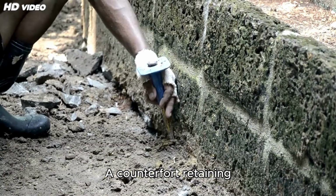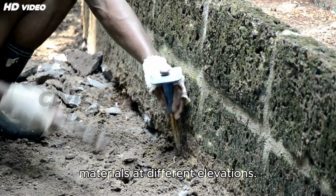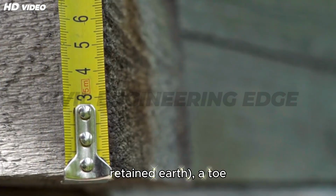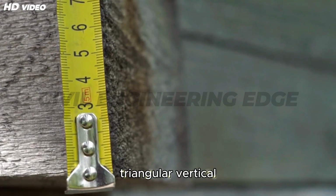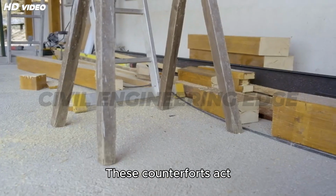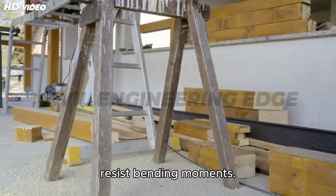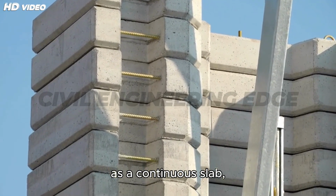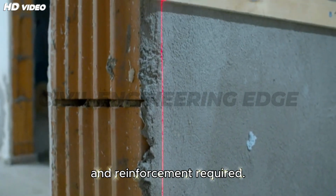A counterfort retaining wall is a reinforced concrete wall used to retain earth or other materials at different elevations. It consists of a vertical stem or face, a heel slab under the retained earth, a toe slab projecting on the other side, and counterforts, thin triangular vertical beams or ribs spaced at regular intervals along the back of the wall. These counterforts act as tension ties, connecting the stem and base slab to resist bending moments. Instead of acting as a simple cantilever wall, the stem and heel behave as a continuous slab, supported by these counterforts, thereby reducing the thickness and reinforcement required.